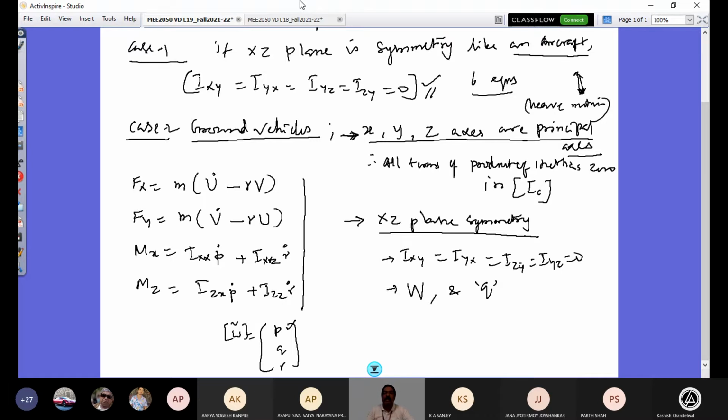When you're accelerating, the load goes from the front to the rear. When you're braking, suddenly the load comes back to the front. That's why we fall forward during braking, right? So that load transfer is there, and the pitch motion is essentially there; you cannot neglect it. And as you drive your vehicle, you don't go straight, you have to maneuver, then you require orientation change. That is why yaw rate is present. Whereas Q is what is pitch here.